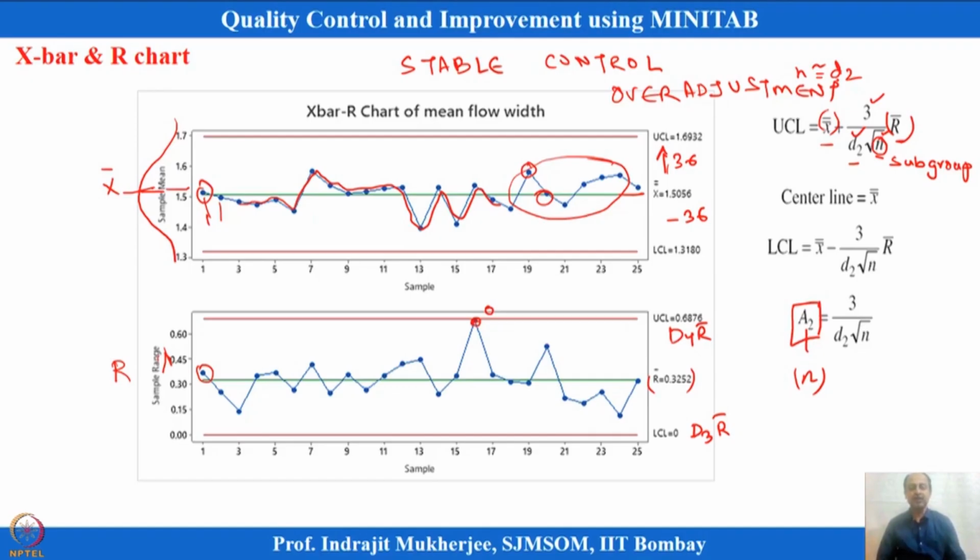In this case one chart is showing change in mean location, and one is showing the precision, and whether there is abnormality in precision. So, if a point falls outside in the x bar chart or the range chart, in that case we have to consider it. At a given time point, if the range goes outside, that means something has gone wrong. So, why variability is high, we have to check. And if the mean shifts to an abnormal scenario, then we have to check why the centering of the process has changed at that observation. So, I have to see what corrective action can be taken or how the centering can be adjusted. Okay. So, one relates to centering and one relates to precision.